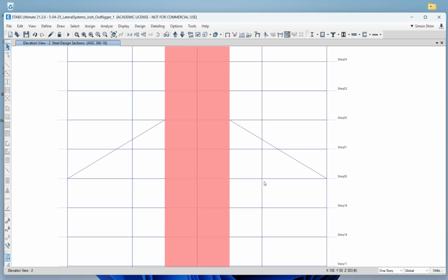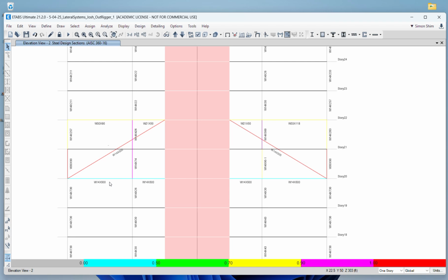All right, so this one, the 14, the 13, this one is still okay, but I use the same size as this because this is really a truss. I prefer that, because we also need a huge connection design here and there. So typically I'll treat this as top chord member and diagonal. Now what I think you see here is something's not right. This is not W30 by 90. This is a column, so it should be part of this W14 by 730.